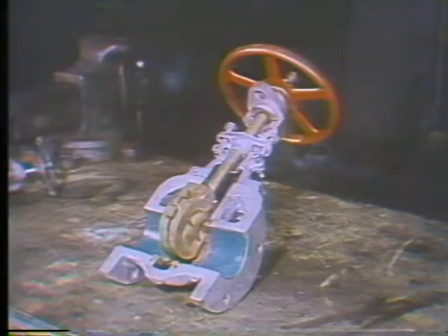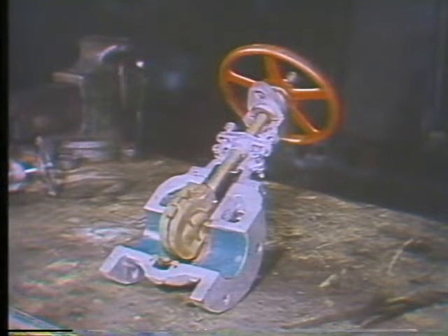We'll cover the 3 most common valves here, but you must be aware that any piping print may have many more valves symbolized on it. Just make sure that you check that legend. This is a gate valve. A gate valve is used to stop and start flow through a section of piping. Gate valves are normally made to operate in a fully open or fully closed position.